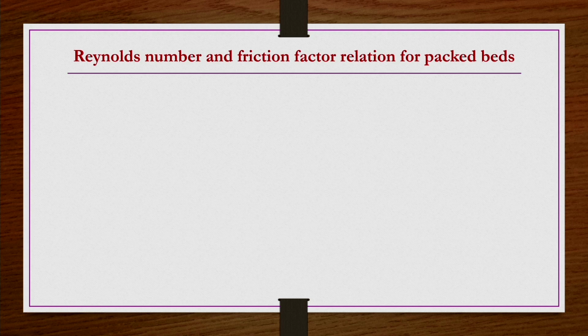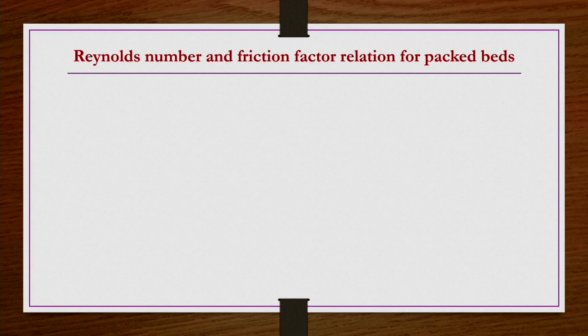But is it the same thing here in a packed bed, when the column or tower is filled with some kind of packing? That is what we are going to see first, and then generalize this Ergun equation in terms of that friction factor and Reynolds number, because that will be an easier way of using this equation for calculations. And they could also serve as a kind of generalized purpose rather than being specific to some cases only. Okay.